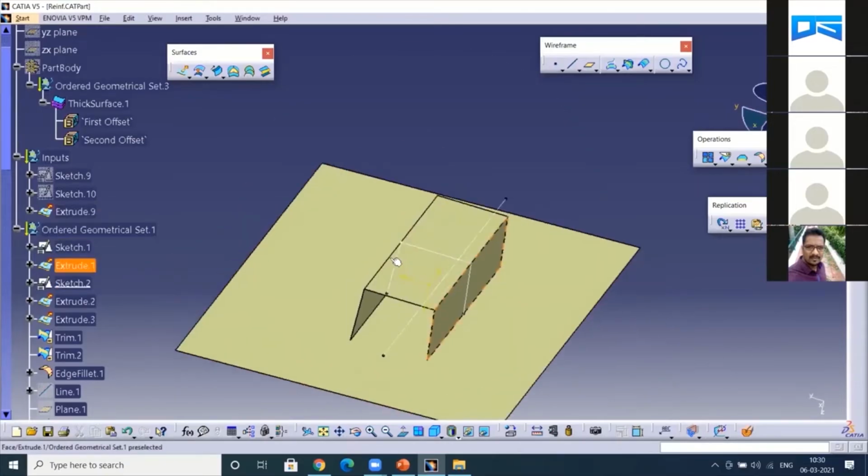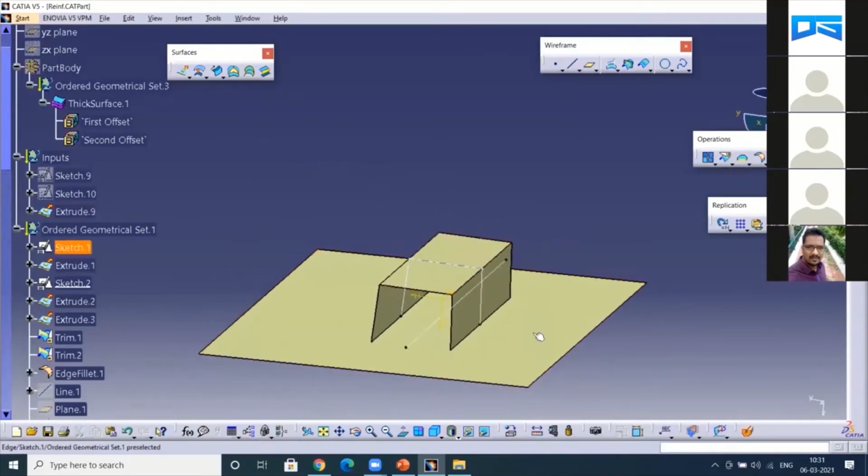In the real world, your sketch constraints will be interfaces. Probably if it is in the underside, you will have your propeller shaft going, so you will have to maintain some minimum distance, or you will have some other lines going. Based on that, you will have to dimension the cross member. The initial step is that the interfaces drive your part. Other than that, whatever target setting points I have told you have to be considered. The part should be strengthened or rigid enough to withstand the loads.